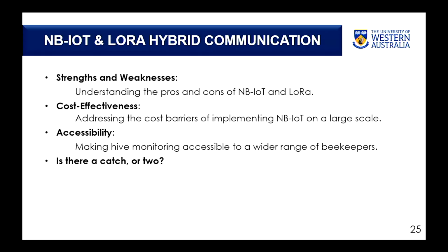What I have done is, yes, my system has to stay awake all the time. But with NB-IoT, I do not keep the NB-IoT module awake all the time. I keep listening to the data, keep adding it to a pool, and when that pool reaches a significant size, I wake NB-IoT up, transmit all of the data, and put the NB-IoT module to sleep. Only the LoRa part stays awake because it is using LoRa to communicate with the local network. That part is awake all the time. This way we are able to save some of the power.